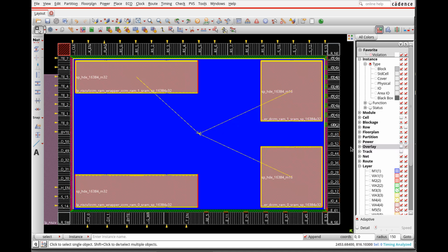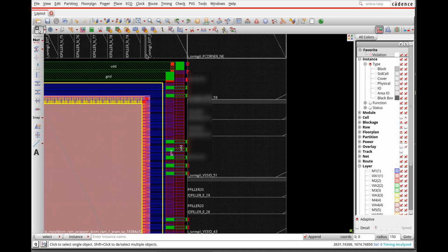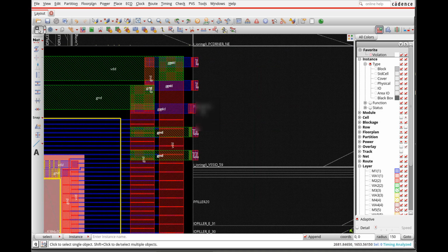I'm going to, again, open up my UI, and remember that all of my VDD and ground pin pads were on the right side, and I can actually see these little things over here. Those are really my connections. So I had this VSS IO59. It had these ground pins, and you see that it made a very strong, robust connection to ground over here.